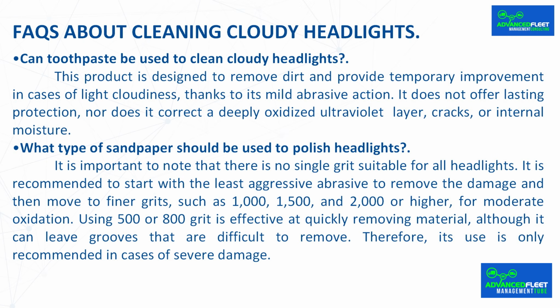Facts about cleaning cloudy headlights. Can toothpaste be used to clean cloudy headlights? This product is designed to remove dirt and provide temporary improvement in cases of light cloudiness thanks to its mild abrasive action. It does not offer lasting protection, nor does it correct a deeply oxidized ultraviolet layer, cracks, or internal moisture.